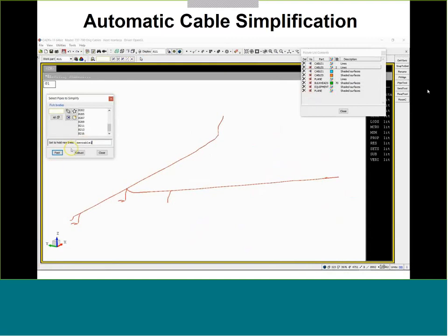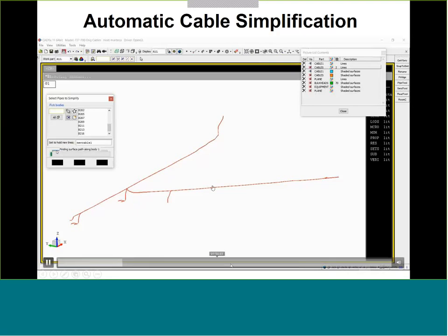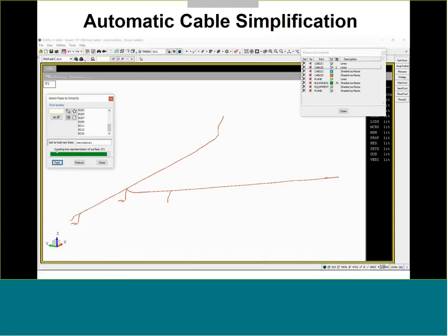So I'm going to skip. Let's say you've got a couple minutes to do all these cables, go get a cup of coffee. I fast forwarded a minute so things go a little faster for today, and you can see we're done. So now we've taken that 3D CAD of the cables and we've turned it into a one-dimensional description that we can do something with. Now we're going to plot those cables as their one-dimensional representation. They're labeled for you, so you don't have to do that. It knows where the branches are in the cable.